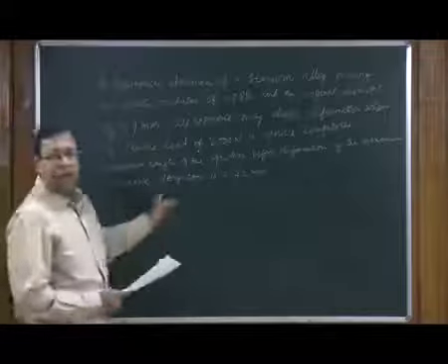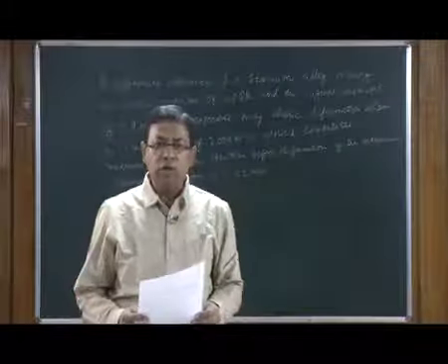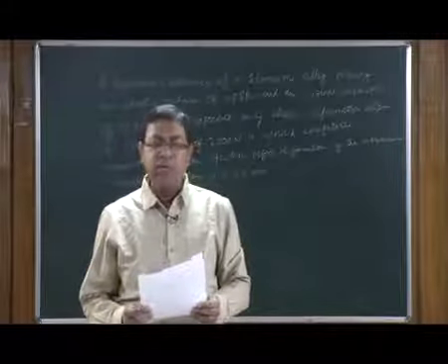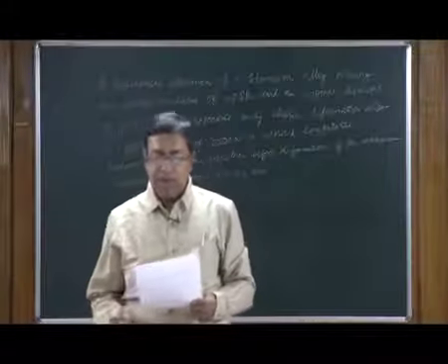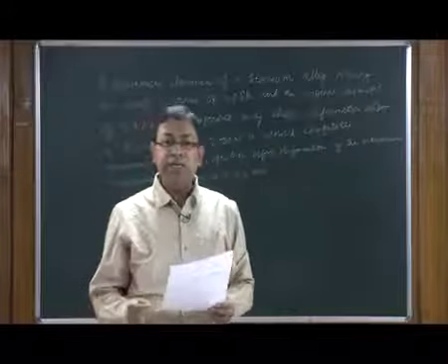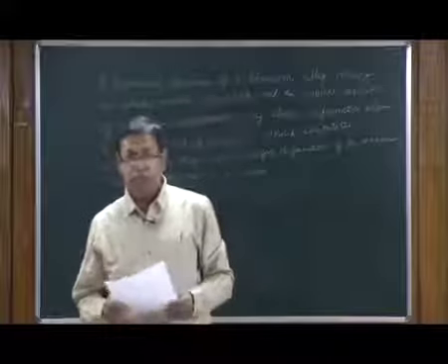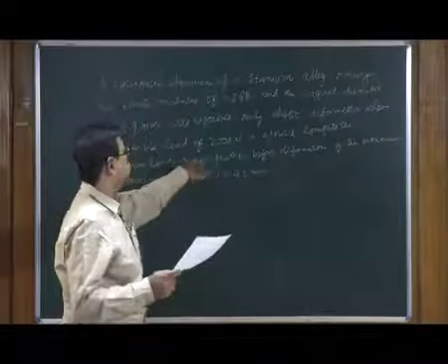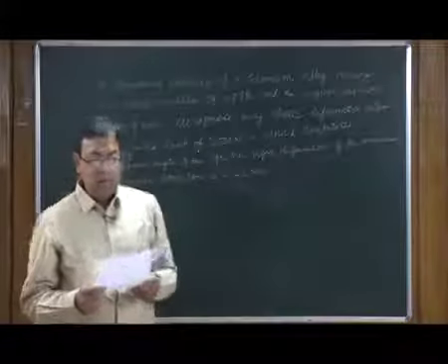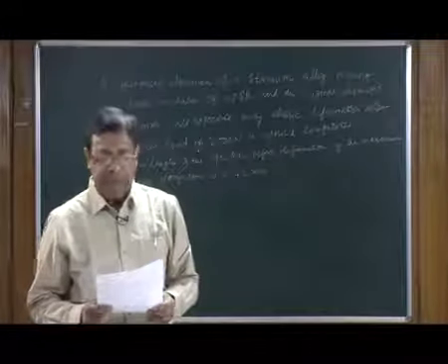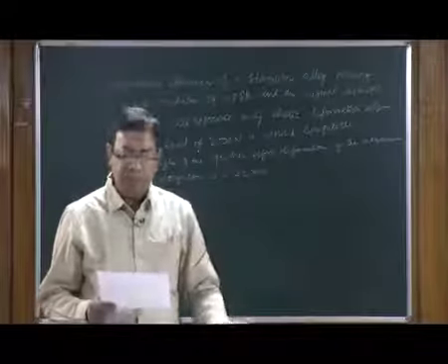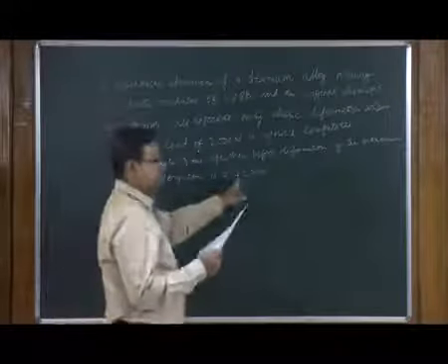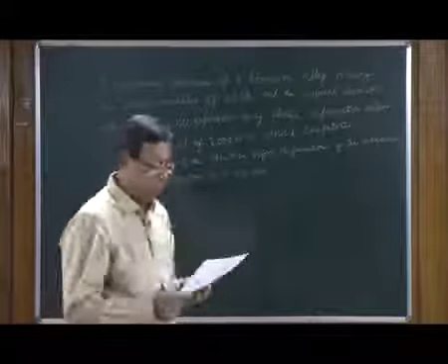So, titanium alloy is given, the elastic modulus or the Young's modulus, which means the same thing in this case, is given and also the original diameter is given. It is experiencing only an elastic deformation, which means we are fully in the elastic limit, when a tensile load of 2000 Newton is applied. So, compute the maximum length of the specimen before it starts deforming, and it is given that the maximum elongation is 0.42 millimeter. Okay.